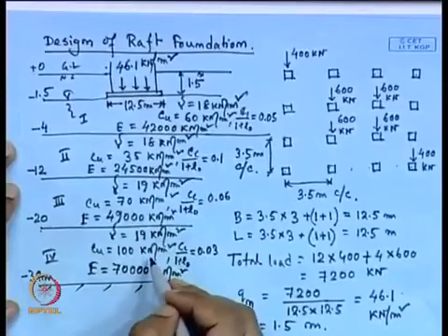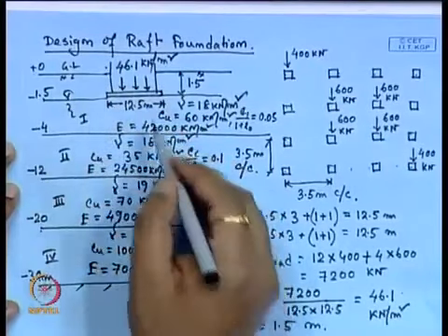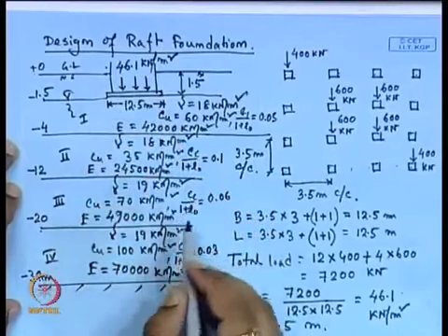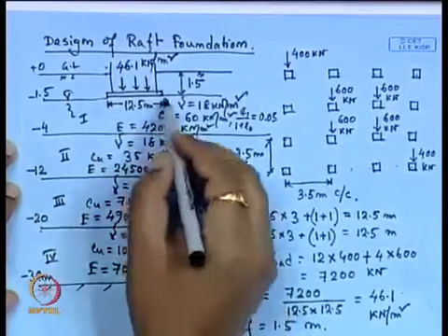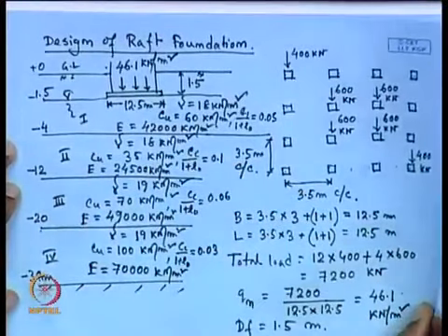So, this influence zone is up to the fourth layer. For the bearing capacity calculation up to the B zone, we take the weighted CU value, or we can take the minimum one for this calculation.